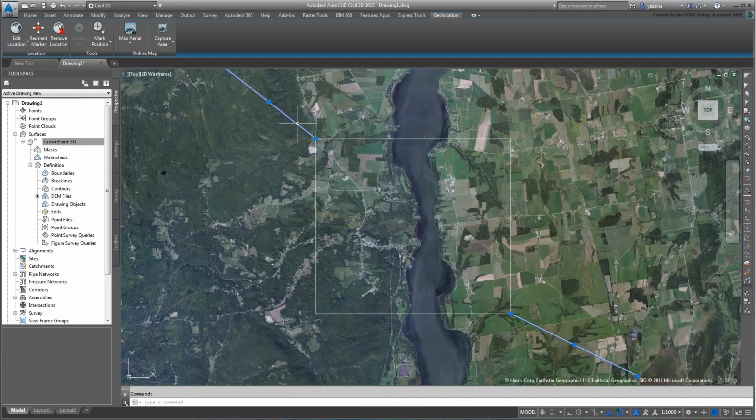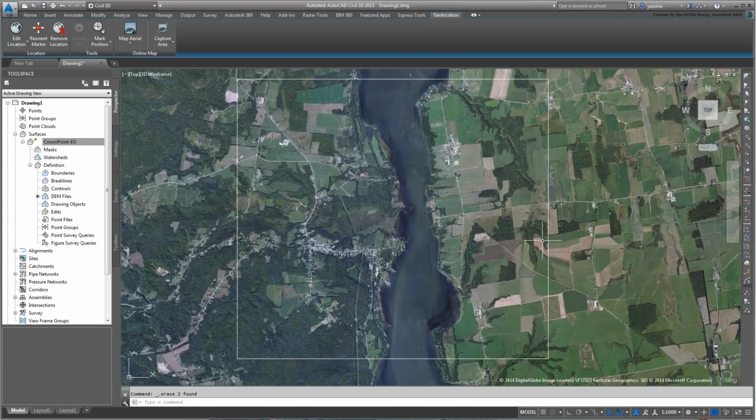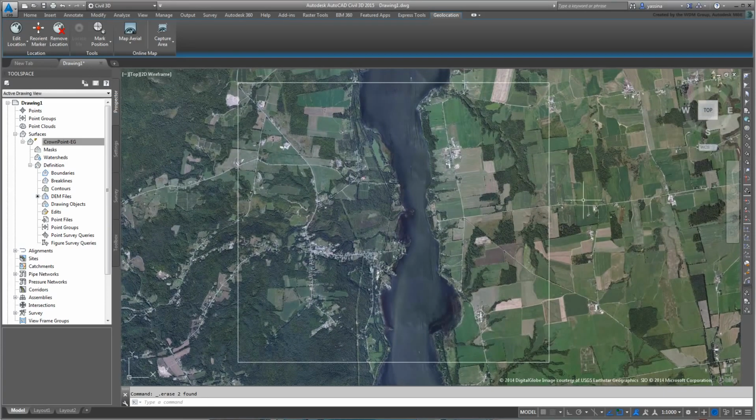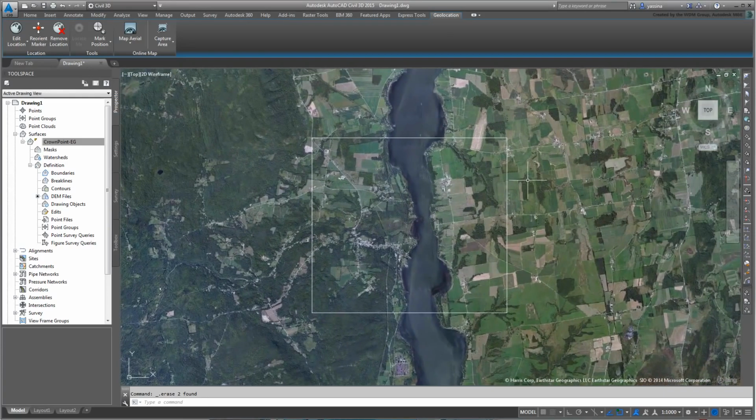The area inside the rectangle is the area of interest. Both the surface copy and the Civil 3D aerial maps will be restricted inside that rectangle. It is also the same size as the texture image you created earlier. This ensures mapping coordinates work well when the map is later projected onto the terrain in 3ds Max.